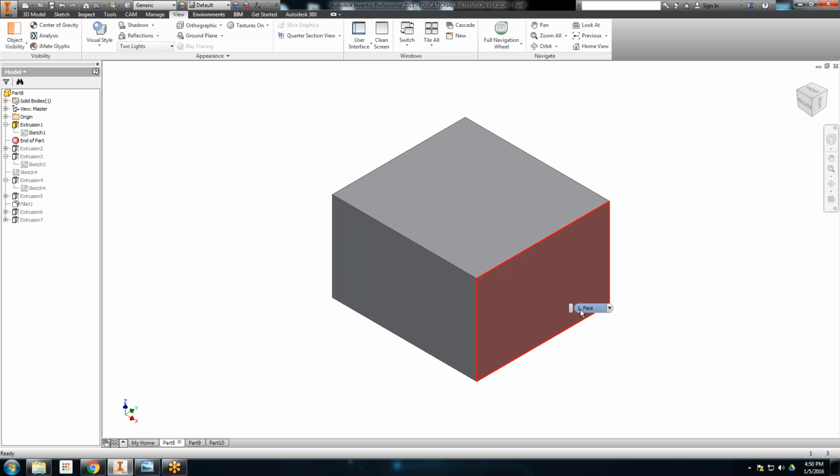That means I've got to go buy a material that's bigger, and you can't go buy a material that's 3 1/8. It doesn't come that way. If I'm lucky, I'm going to get a 3.5 by 3.5, or if not, I'm going to go up to a 4, and I'm going to have tons of wasted material to be able to make this. So what we do instead is we design it out of the stock rather than design it and then try to find stock to fit it.